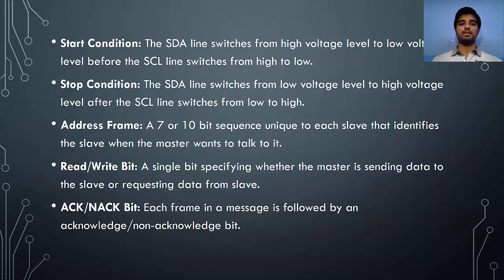Start condition. The SDA line switches from high voltage level to low voltage level before the SCL switches from high to low. Stop condition. The SDA line switches from low voltage level to high voltage level after the SCL line switches from low to high.